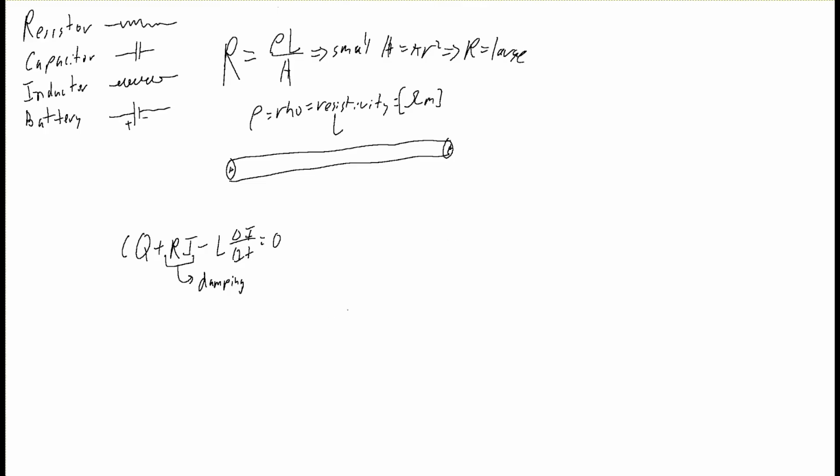The problem with my inductor, with this really fine wire, is that it implies about an ohm or two of resistance, which means that in order to have an oscillating circuit, I have to make the capacitance really high.